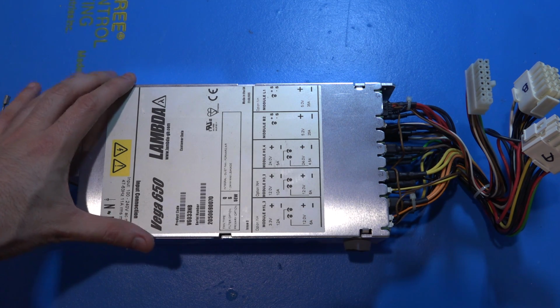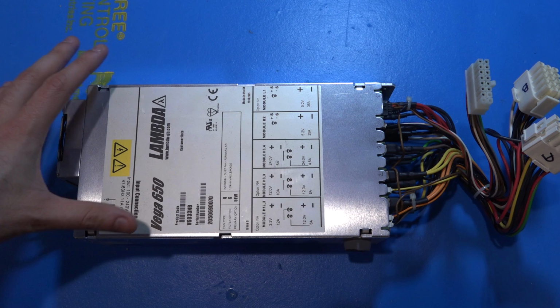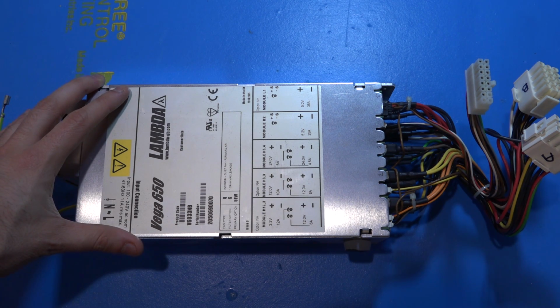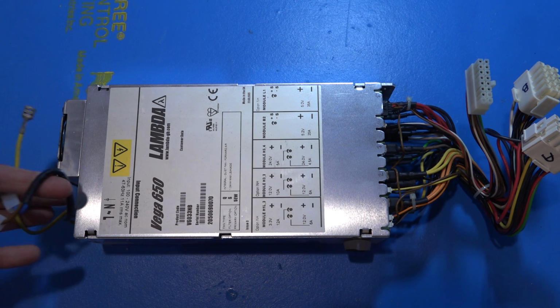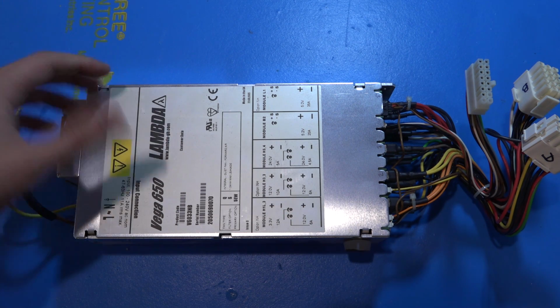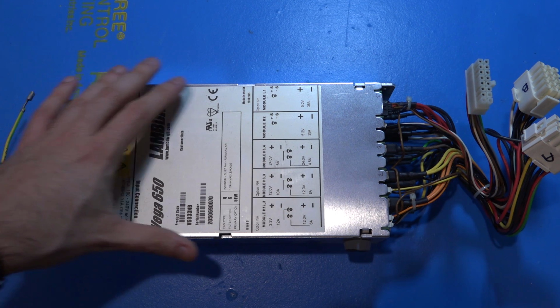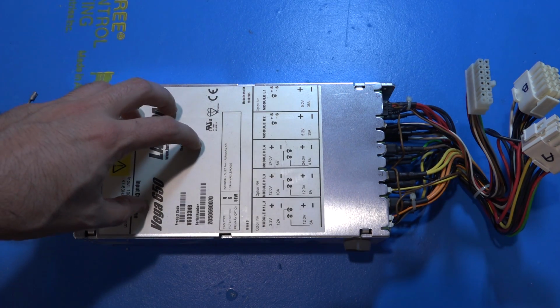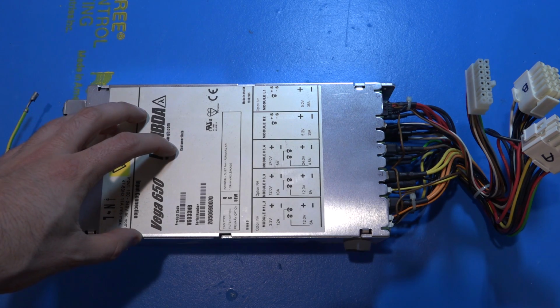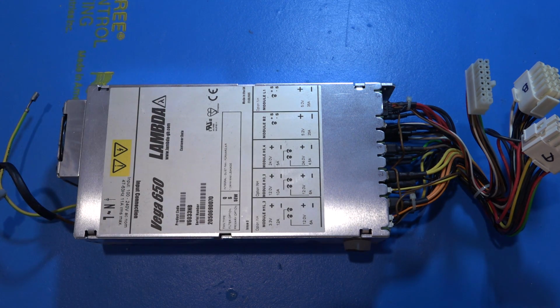And I can do a quick search on the internet, see if there's any information about it. I doubt that these things are kind of protected in terms of schematic and so on. We're going to have to open it up and take a look. We can just work our way in from the AC signal and see what happens. And if we can find the standby voltages, it's unlikely that all the modules have failed. It may very well be that the front end is bad, which would make it a little bit easier to fix. But first, we're going to do a little bit of reverse engineering, a little bit of investigation before we do anything.